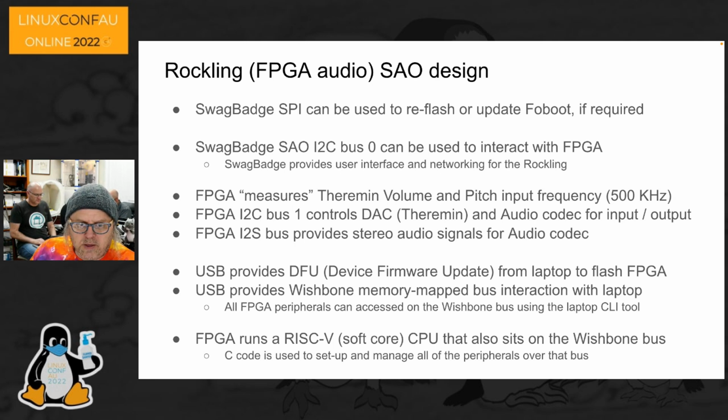So the FOMU normally comes with a RISC-V soft core that's quite capable, but it also consumes quite a lot of resources. So Andy was able to find a smaller implementation of RISC-V called FemtoRV, I think it was, which didn't use quite as many logic cells, as we were running out of room.